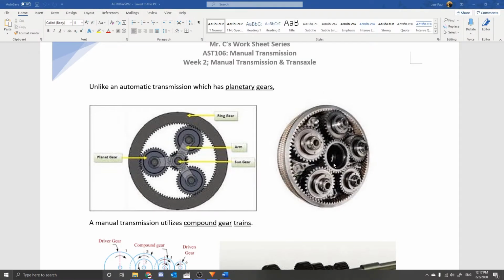So let's get over here. Planetary gears. These are very common in mechanical engineering all over the place. So if you Google planetary gears, you'll find them in, if your wife or mom has a mixer in the kitchen, it's got one of those. Dump trucks use these. Helicopters, planetary gears are super common because they're super efficient. And what's interesting is I'm just going to note this quickly. These gears are always meshed together.